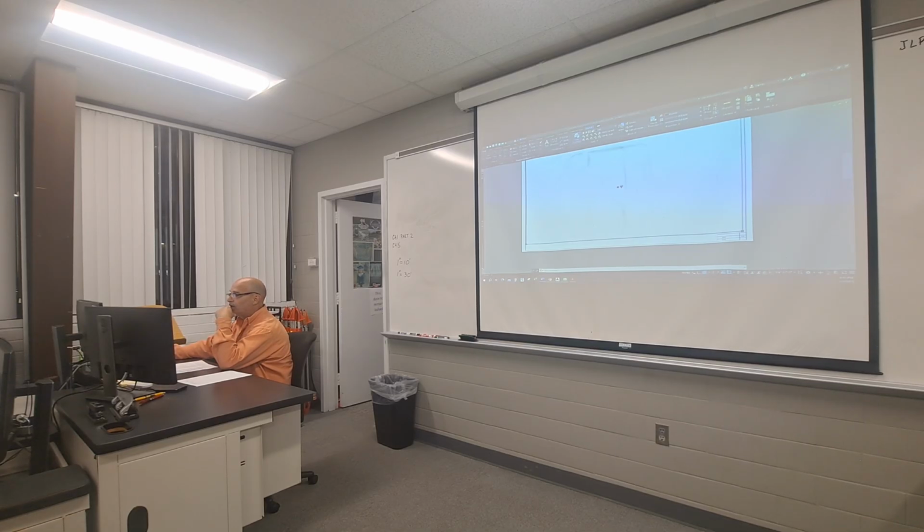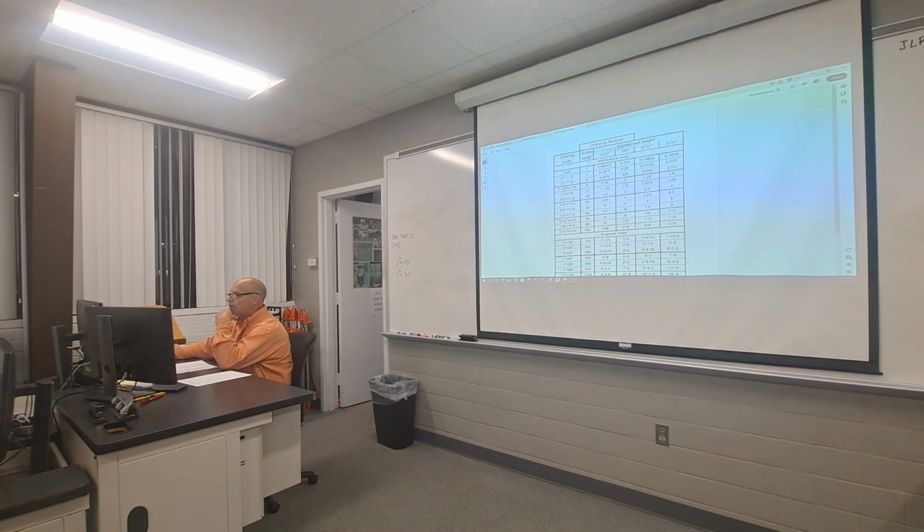Now, on the handouts that I put for you in Blackboard, one of them had on the bottom these engineer scales. Like I told you, an engineer scale always starts with 1 inch equals. 1 inch equals 10 foot, 20 foot, 30 foot. Now you'll see this next column right here. At the top, I call it the scale factor.